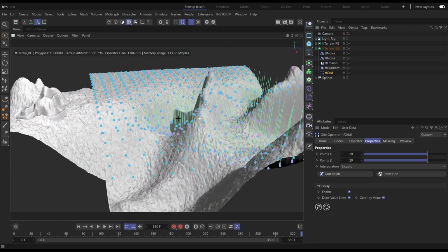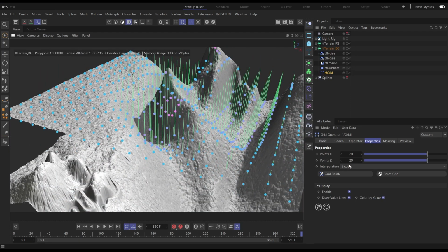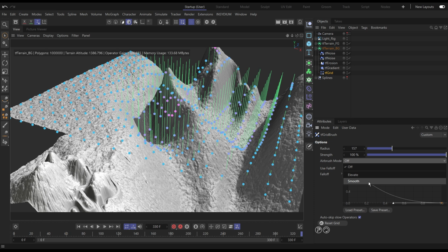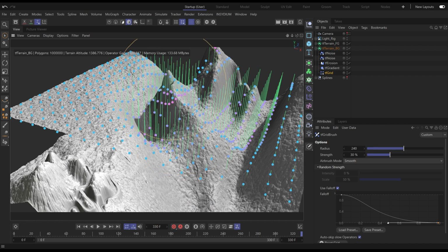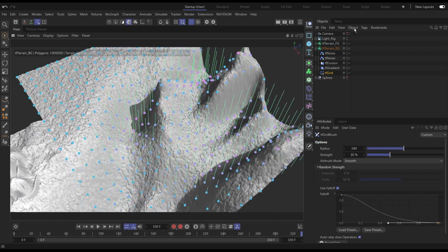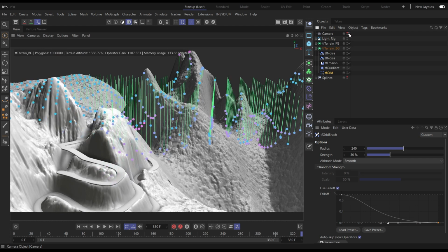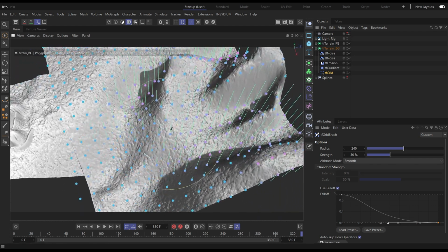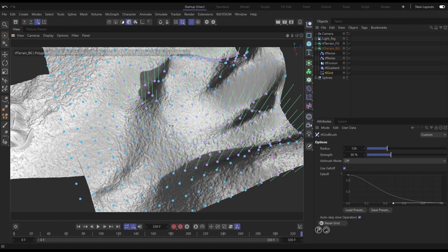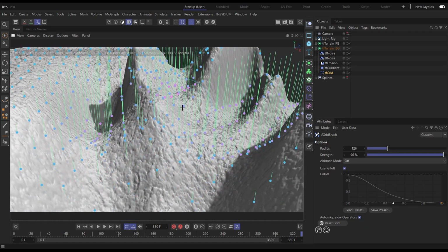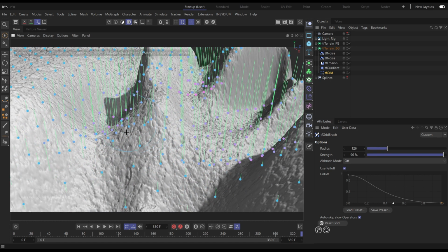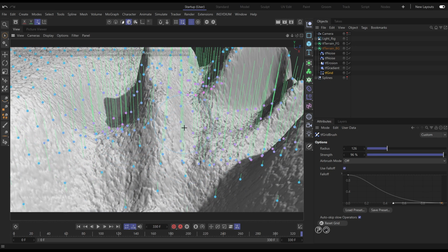Now we can go into the smoothing brush. So we'll go into the grid brush and change the airbrush mode to smooth, and let's just bring down the strength and smooth that area off a little bit. And that's looking a lot better. So let's have a look. We will smooth off that valley just a little bit more, then turn airbrush mode off. We'll reduce the radius and increase the strength back up, and then let's drop both sides of the valley down and keep that ridge nice and pronounced.